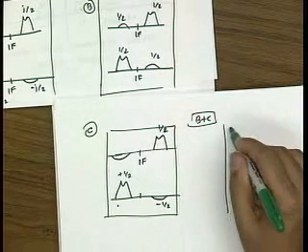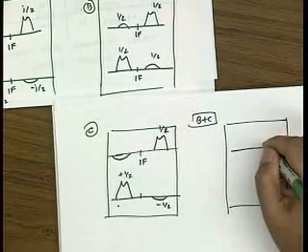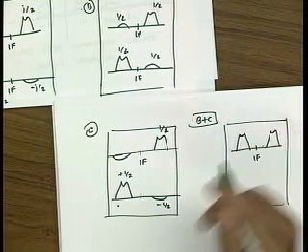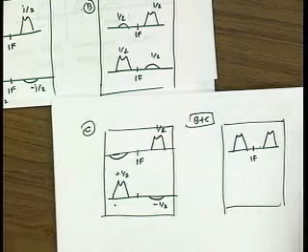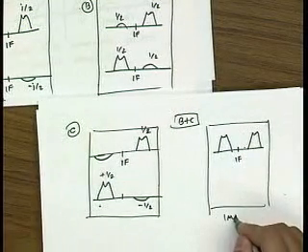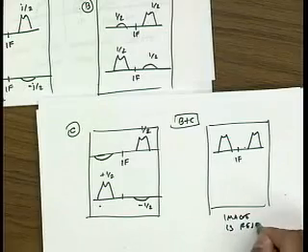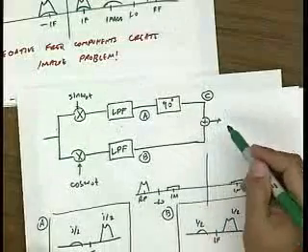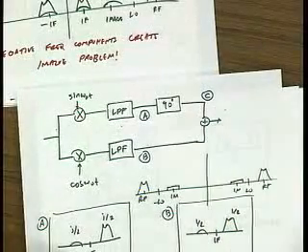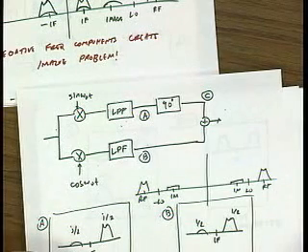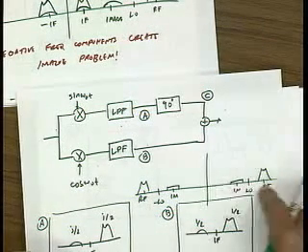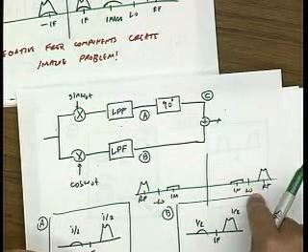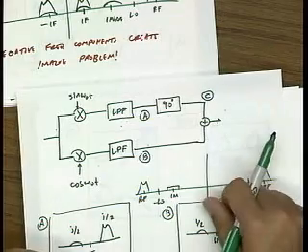So what I end up with is exactly what I want. It's my signal which gets down converted, and my image gets rejected. And you can easily verify that instead of adding these two signals, if I had subtracted, the image would have made it through and the signal would have gotten rejected. And of course, which one is your image and which one is your RF is kind of arbitrary. It's whatever you like. Remember, I can either inject my LO above or below the signal.